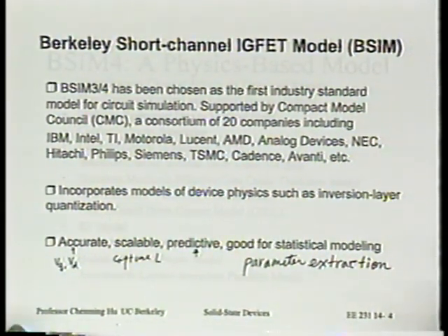You can try to model all this dependence accurately by putting a lot of fitting parameters into the model, because the more fitting parameters, the more you can adjust the model to fit the details of the data. Well, people have found out that just by adding a lot of fitting parameters, because that's needed in order to get a chance of fitting, parameter extraction becomes very difficult, because these parameters, as you throw them in at random,